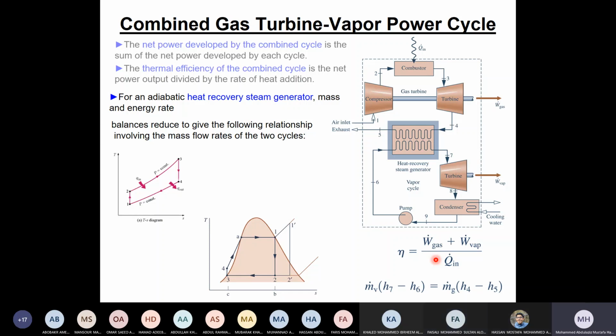It's important. I know you complained about the binary cycle, but this is a real cycle which is binary. It was similar to this, but this was ammonia and this was, I think, gas. So we always want to use the temperature here to solve that. So you can have a Rankine cycle here, but this is the well-known combined gas turbine cycle, and it is in Korea now. We have one plant in Korea for combined gas turbine, and it will be available everywhere in the kingdom very soon because you change the efficiency from 30% to around 55%, and this is why it works now for saving energy and so on.